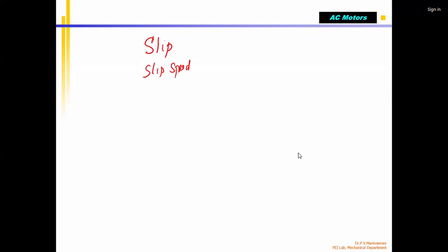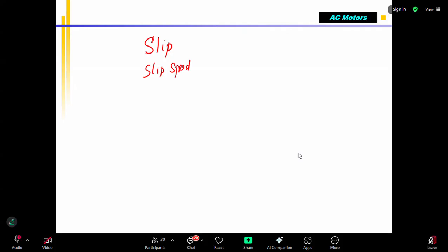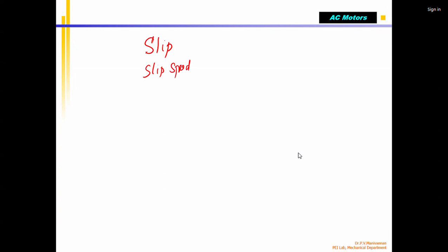Sir, I have a question. Can I ask if you allow me? Definitely, please. Professor, in the last class, you taught us regarding synchronous motor. You taught us that three-phase current is provided in the stator, and a DC supply is provided to the rotor. By aligning that, the rotor chases the rotating magnetic field, and that is how the synchronous motor works, right? Correct. So for starting a synchronous motor, we have to have an external DC supply to the rotor, right, sir?